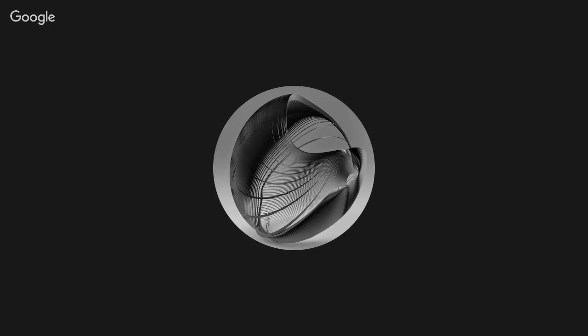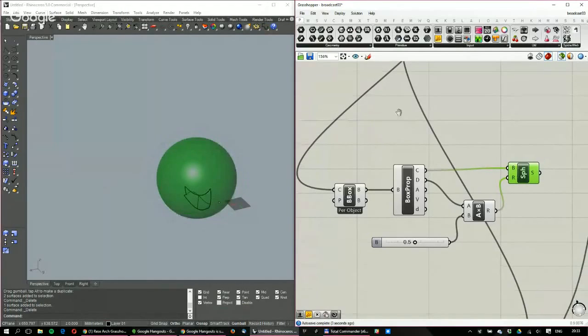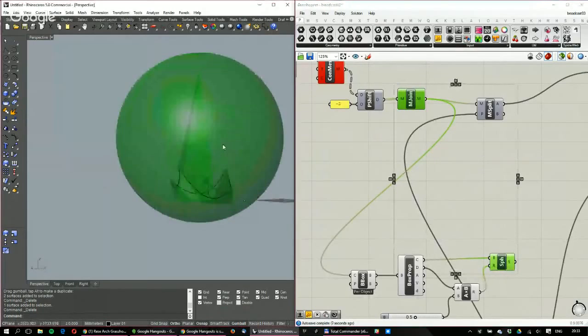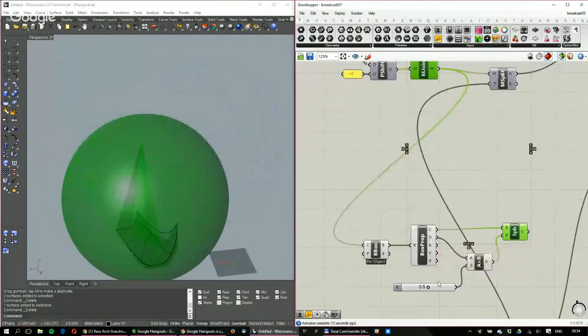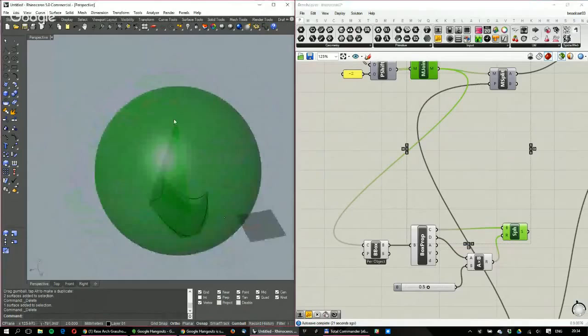It seems like my internet connection should be much better to actually do these things, but nevertheless, I created some bounding sphere. So basically, I took the bounding box, took the central point and the diagonal, multiplied by 0.5 here, and created a sphere. I created this sphere because I want to use the DLA.